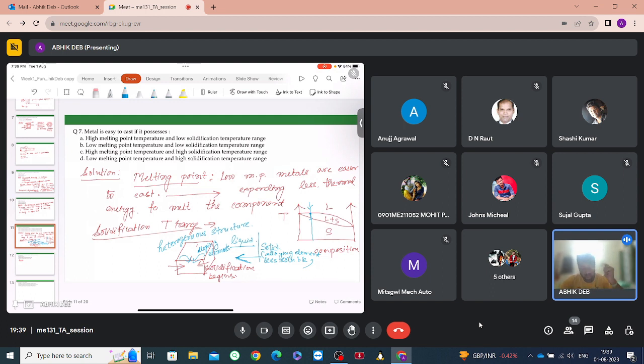It is this difference in the solubility, or transfer of this alloying elements from the solid to the liquid region, that is causing the problem. So the existence of the liquid plus solid region is causing this heterogeneous structure. Is it clear to everybody? Yes, sir. Okay, so when there was no liquid plus solid region, there is no heterogeneous structure and no problem. And when this liquid plus solid region is existing, there is a heterogeneous structure and there is a problem.